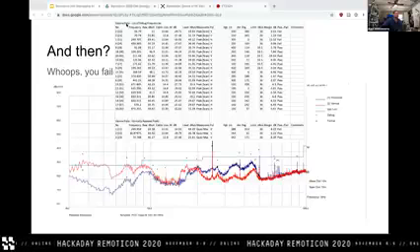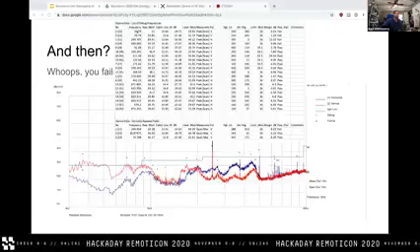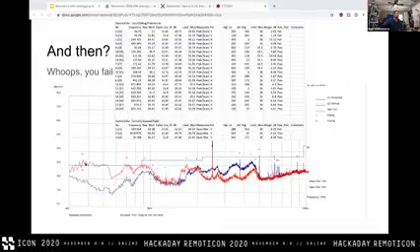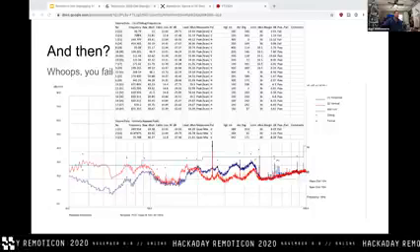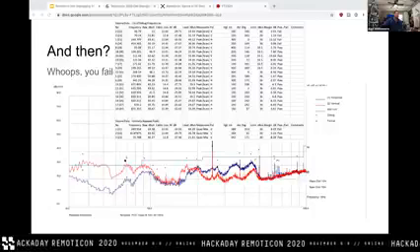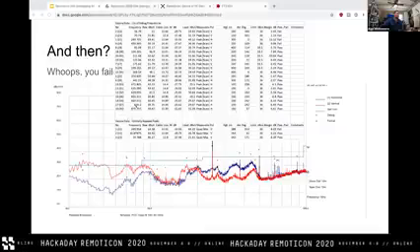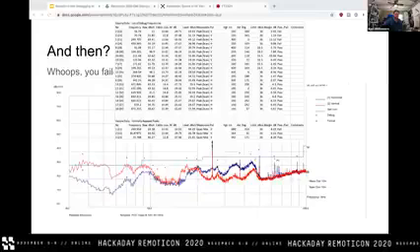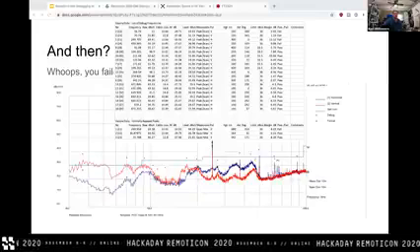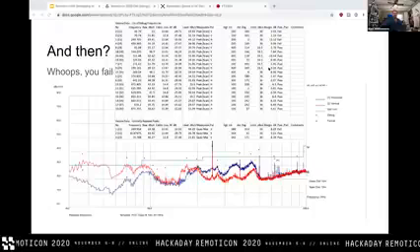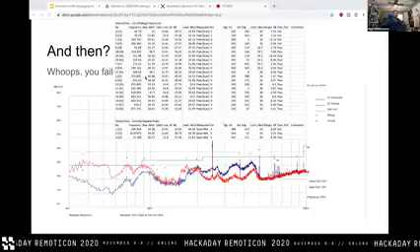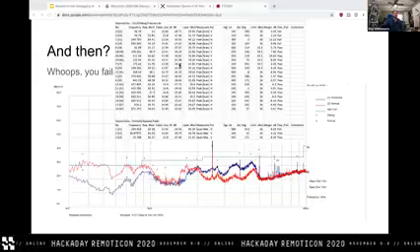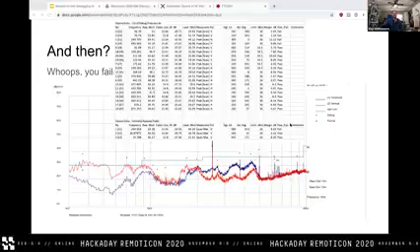So up here in the debug frequencies list, we see there's a worrying peak at 36-ish megahertz. So that's like this guy. There's another one at 70 megahertz. So I think that's this one. There's another one at 250 megahertz. That's these two big peaks, and so on and so forth. So, okay, we've got to go figure out what on our product is emitting RF interference at those frequencies and tamp that down, right? Well, not exactly.